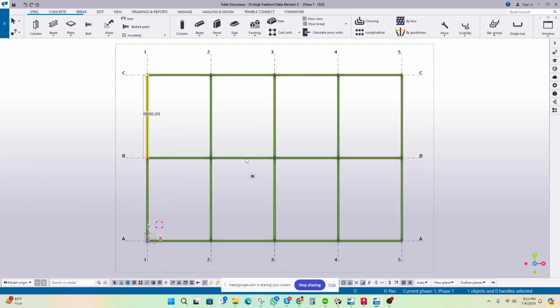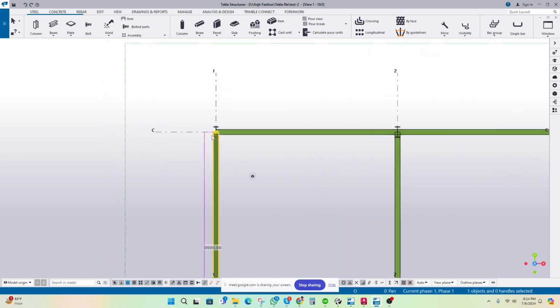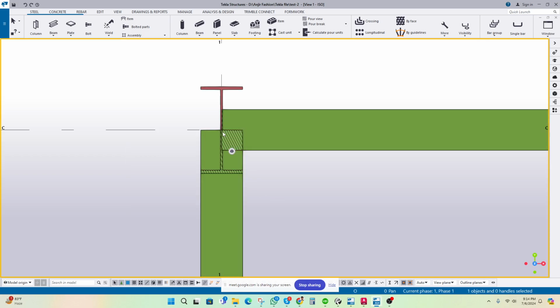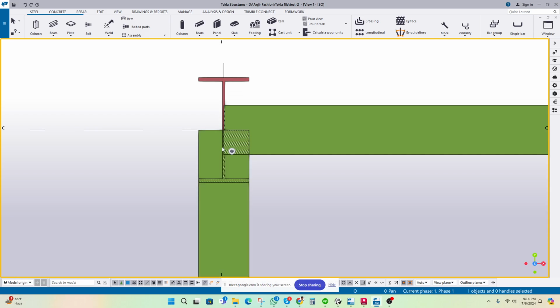For example, as I see it in a plan, I just make the modeling center to center, not the edge of the column. When I connect it, because my force and everything will pass through the center, for this reason we also make the member placement from the center. So when I make the connection, it will be cut by the edges. That's my default.